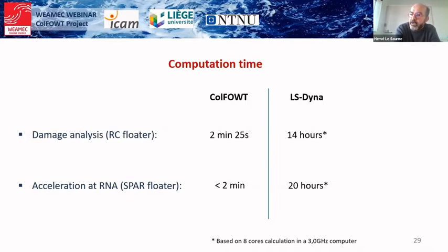Regarding the calculation of accelerations, with the ColFOWT program we can assess an acceleration in less than 2 minutes. The main time concerns the eigen solution, that is a calculation of natural frequencies and mode shapes. But with an explicit calculation using LS-DYNA, we need around 20 hours with a model based on shell elements.